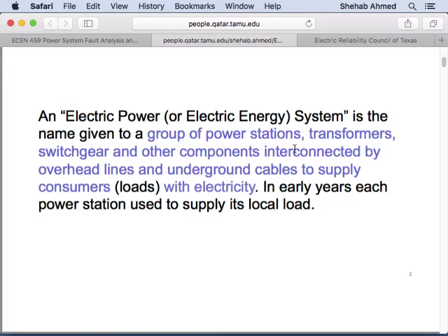A similar thing. So you have a generator, and you have a load. You want to connect them with a transmission line. This transmission line will be connected to the generator. How will it be connected to the generator? At a node. This node we call a bus bar. This bus bar is nothing but some pieces of copper. So as the word means, a bar that we call a bus in the system. So if it's a 3-phase system, and typically all systems that we deal with will be 3-phase, there will be 3 bars in the substation.